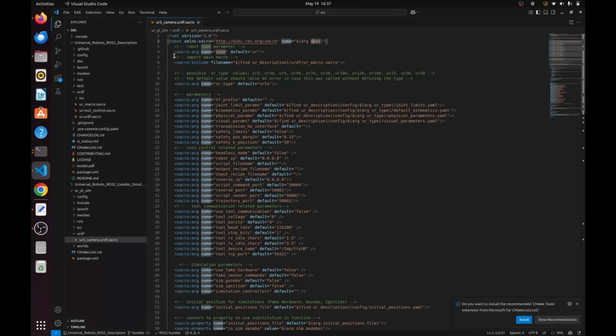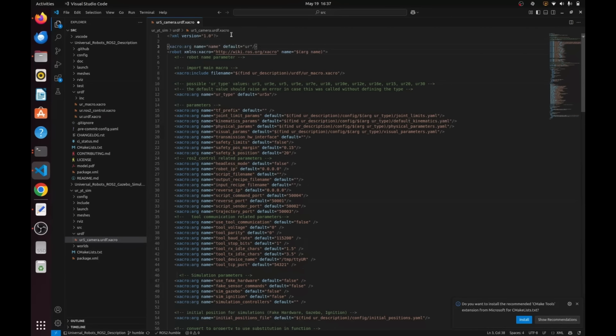If you put it on top like this, for example, it is going to be a problem of xacro, but MoveIt will recognize it because it associates the name to here. If you keep it like this, MoveIt is not recognizing it. So the first modification of the file that you need to provide is this one. You provide a name, that's all.